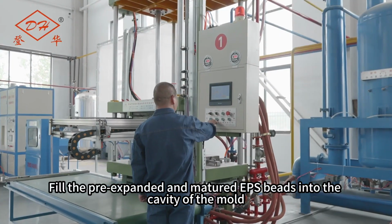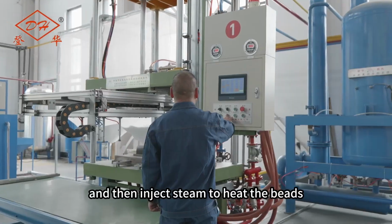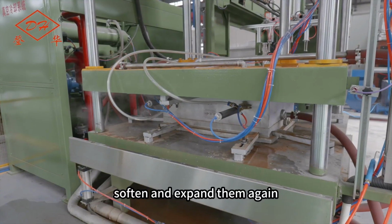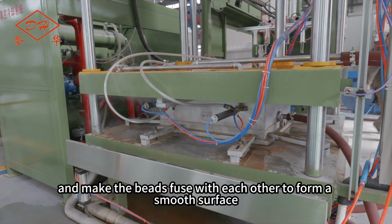Fill the pre-expanded and matured EPS beads into the cavity of the mold, and then inject steam to heat the beads, soften and expand them again, fill the gaps between the beads, and make the beads fuse with each other to form a smooth surface.